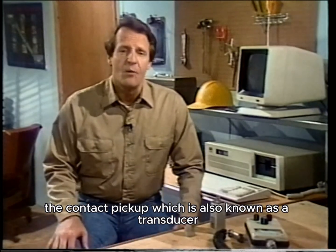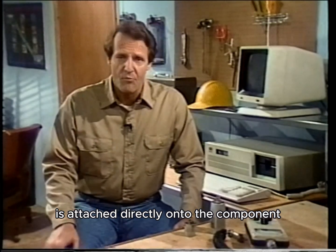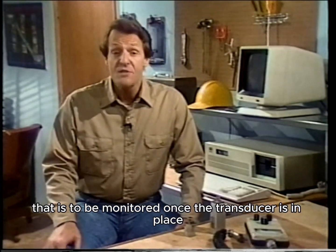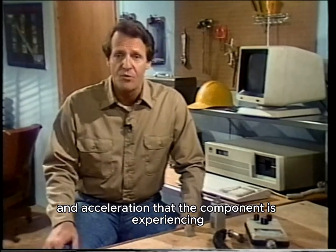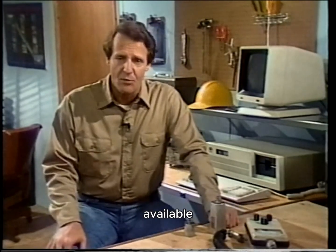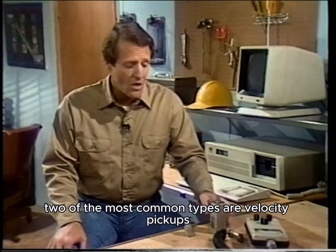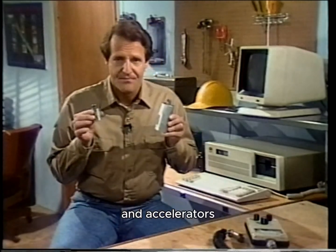The contact pickup, which is also known as a transducer, is attached directly onto the component that is to be monitored. Once the transducer is in place, it can detect the amount of displacement, velocity, and acceleration that the component is experiencing. There are several different types of contact pickups available. Two of the most common types are velocity pickups and accelerometers.